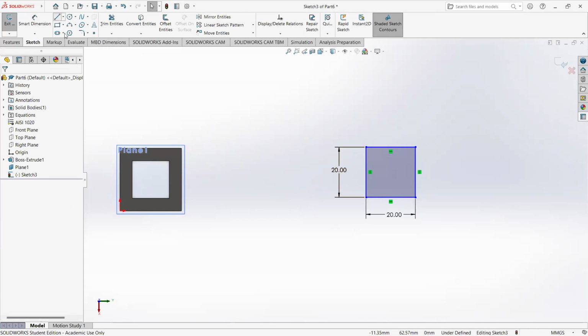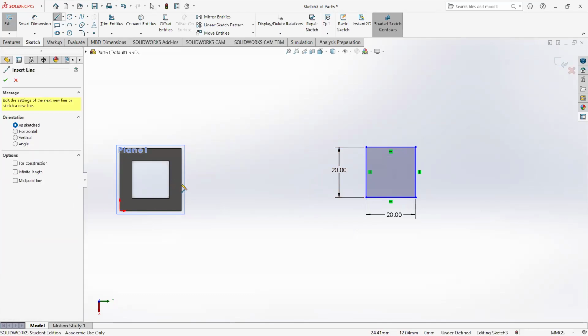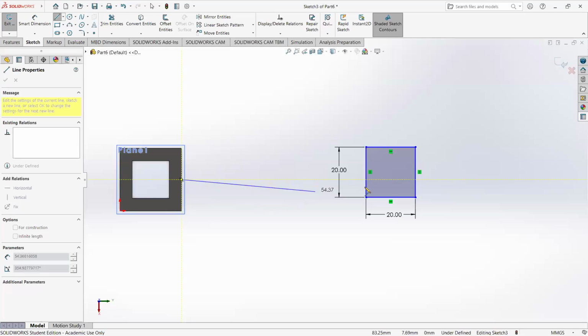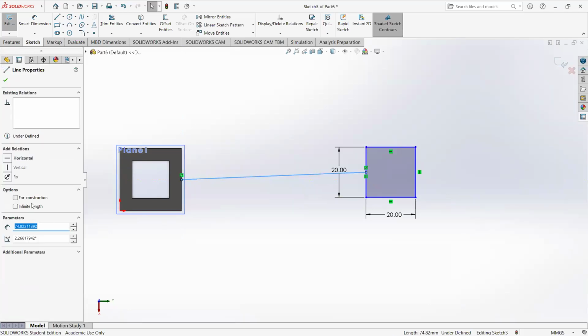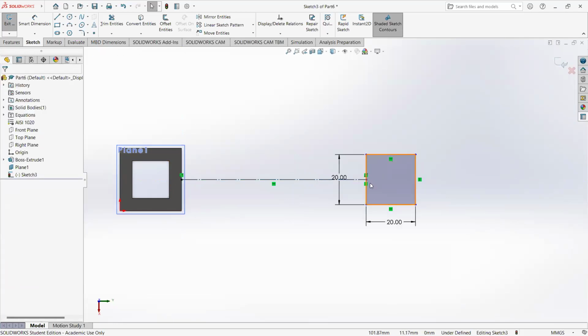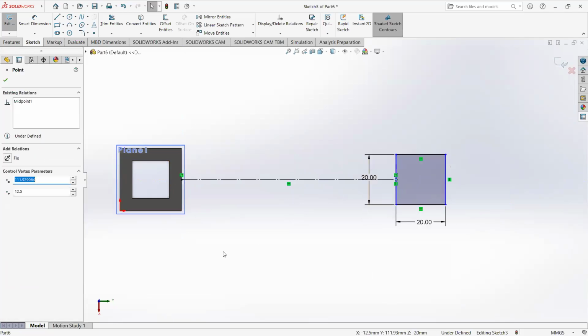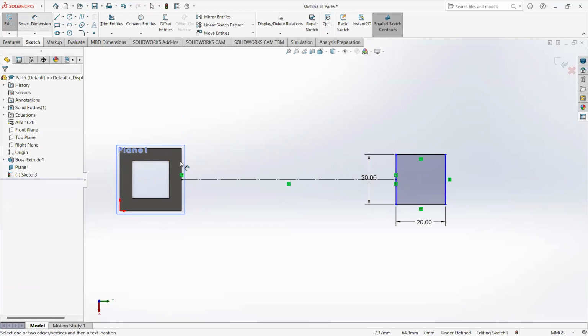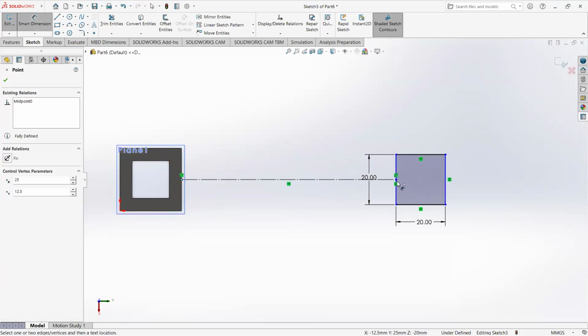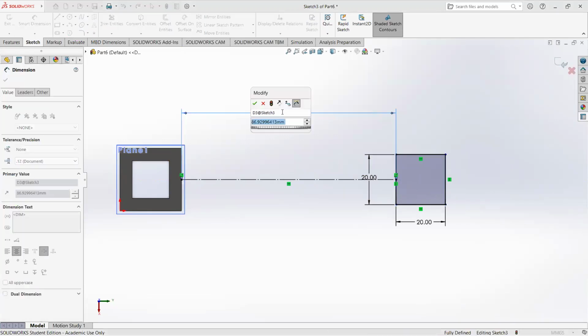Now these things need to be in line. It was a straight part. So I can just move my mouse over till this goes orange. And in the middle, I can wait till I get the icon for center point, rather. I can drop a line from center to center. Remember to make that for construction. And I can fix it to be horizontal. Now those two things are locked horizontally, right? And then the distance between them is what I want to set as A. So I'm going to set this equal to, don't forget the quotation marks, "A". Enter.